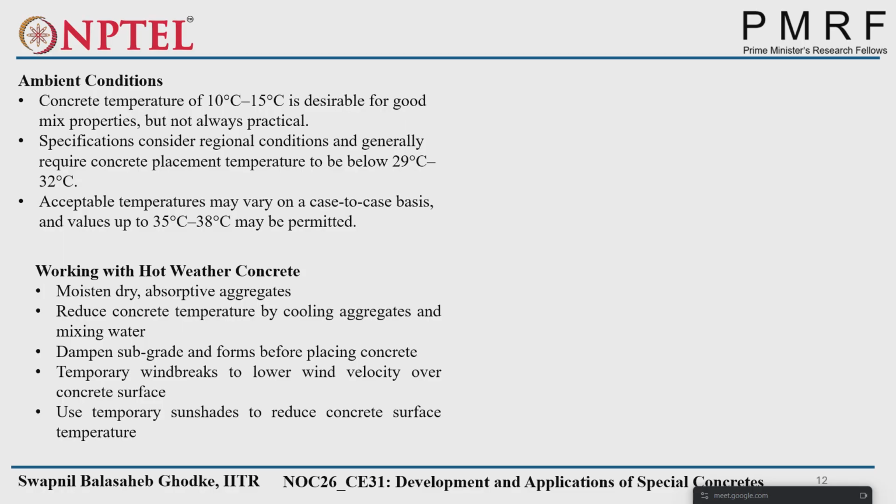I think those are from industries. You will see some construction sites have a chilling plant also, where they will use cold water in the concreting. And for aggregates cooling, on the site most of the times we will have the warehouse for the cement, but will not have the warehouse for the aggregates. Aggregates will be placed in open space only. But in hot weather conditions, aggregates should be covered, so that the temperature will not be that high.